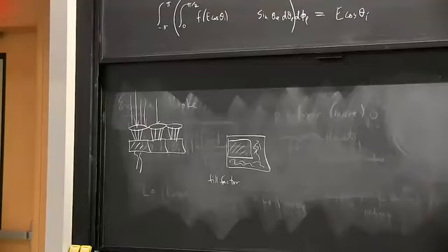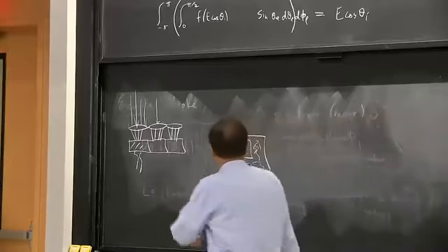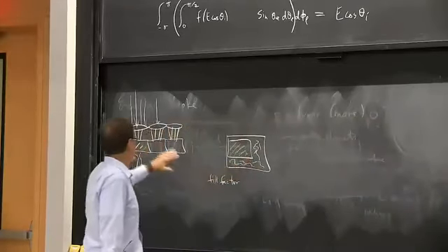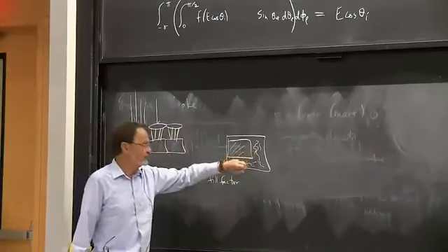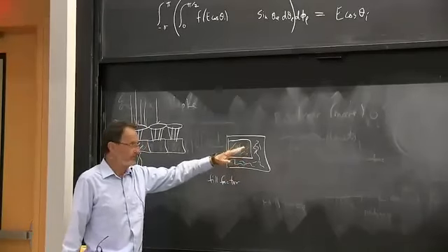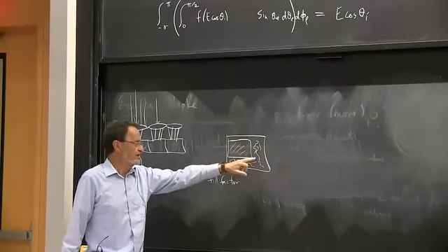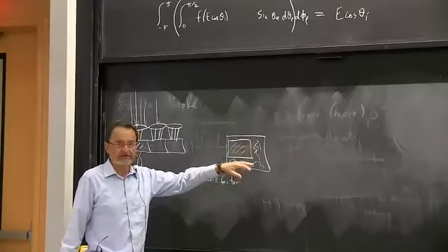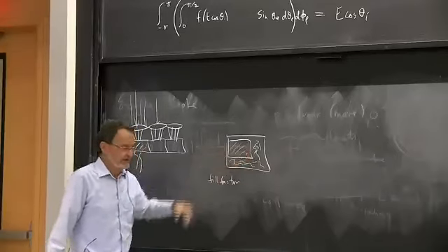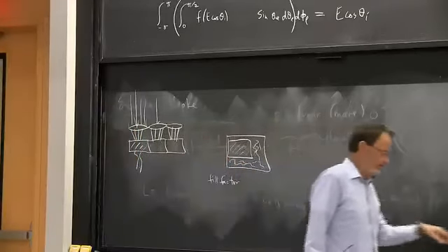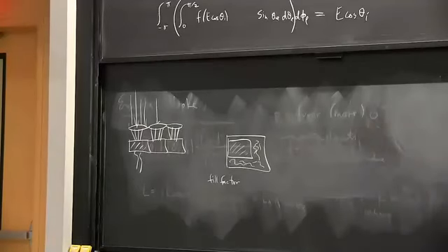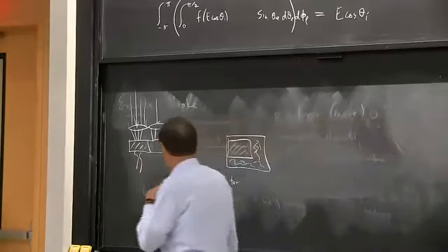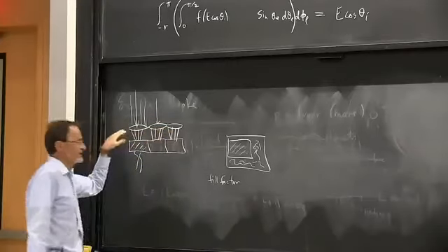Okay, so there are different issues. One of them is, if you image without the lenses, you're throwing away light, not measuring it. What's worse, you have to protect this circuitry from the light because light goes into the semiconductor, creates electron-hole pairs, and if that's right in the middle of your MOSFET, that's not such a good thing. So that means you have to put a metal layer on top of it. So that's one reason why people add the little lenslet arrays.